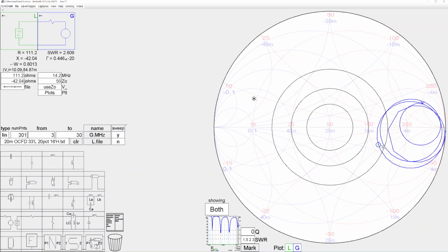I think that's going to be the shortest path because I'm a negative impedance. Notice at 14.2 megahertz, I'm at minus 42 ohm. How do I know that? I can inspect it by just simply clicking on the bubble, and at 14.16 megahertz, I've got an SWR of 2.795, and I've got a Z of 1.09, which is above 2 times 50, and a negative 53 j ohms.